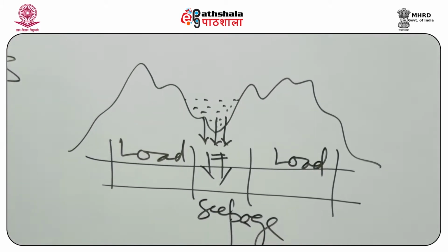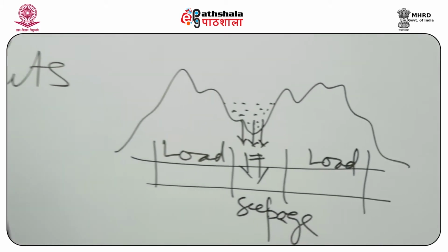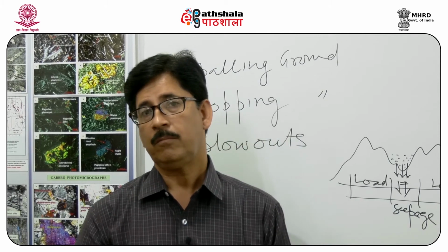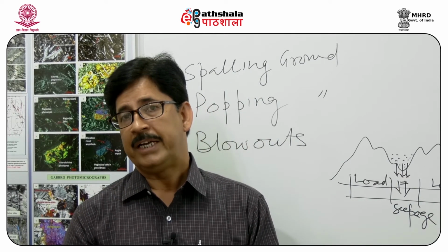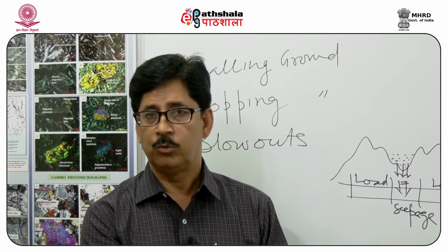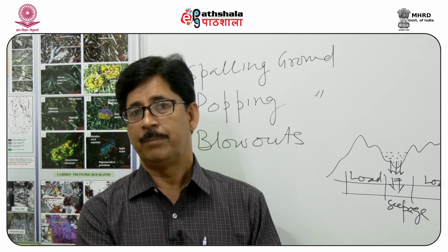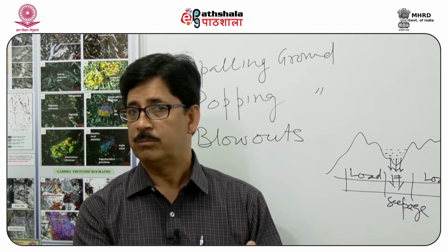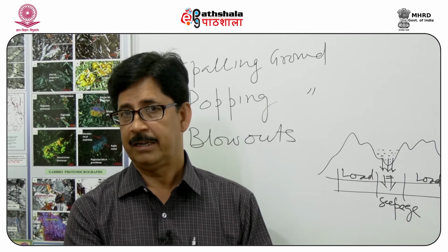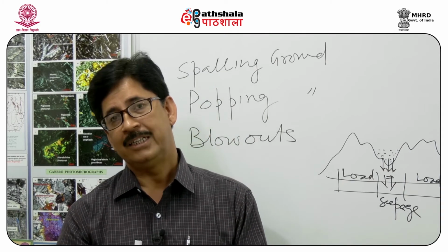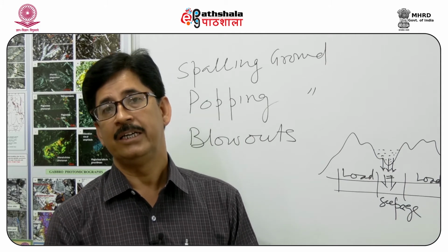So geomorphology is very important because it is going to control the overall load on the different sections of the tunnel. If we are making a tunnel through a hill, and you go close to the slope, then the problem of rock mass movement will be very high. If you make your tunnel through the middle of the hills, then the length of the tunnel will increase.